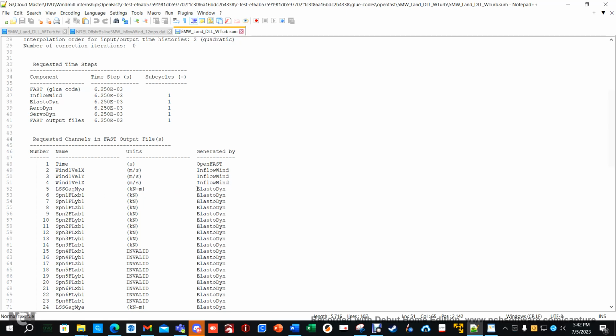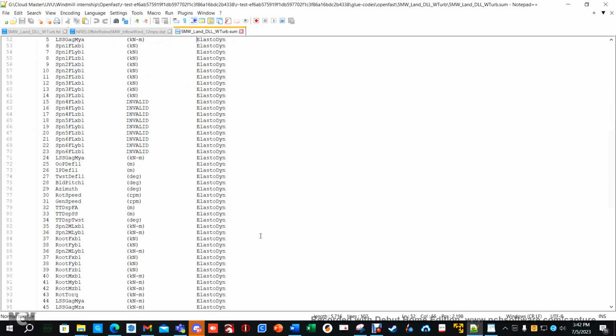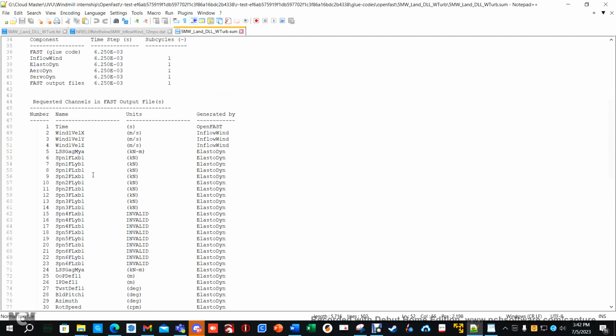And it was performed by another program that is already in the files. It's called ElastoDyn. And all of these are done by ElastoDyn. There's actually 59 tests that it did. So B1 is blade 1. These are different flexes across them. Some of these aren't going to work like 4, 5, and 6, because notice it stops at 3. This is for a 4-blade turbine, 5-blade, 6-blade, which I don't even think they make, so I'll show you how to edit the correct file in a minute.